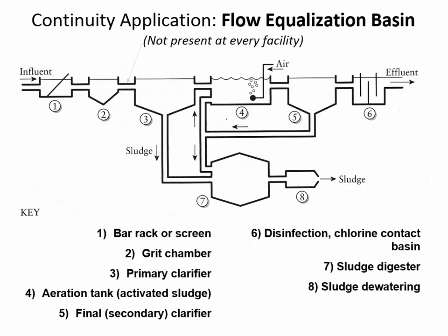The second thing is a grit chamber. Something related to fluid mechanics when we get into environmental engineering is little pieces of sand that, if left in there, could cause a lot of erosion and scour inside of pumps and pipes. So we have to remove that early on. It's interesting to calculate how quickly sand particles settle down through fluids. It's related to the viscosity of the fluid, the diameter of the particle, and the shape of the particle. That's an interesting fluid mechanics application you'll get to later on in order to design the required size of a grit chamber. The next step, step 3, is a primary clarifier, which removes the solids that either settle to the bottom or float to the top, meaning suspended particles that are a different enough density that they'll float or sink.